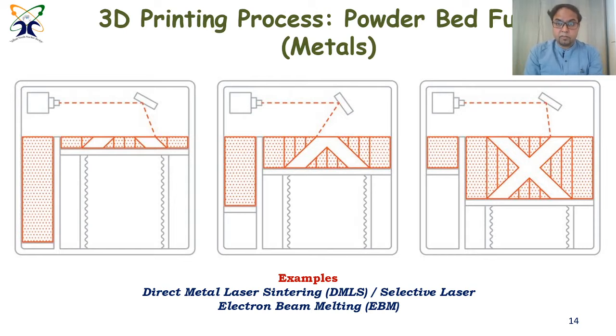This is another powder bed fusion dedicated to metals. Here we use a laser to melt the specific design or specific area, to melt the powder boundaries, to convert it into melt, and then fuse it to form a solid metal body. And this is very unique because the precision is high, you have high energy and a very penetrating, low diameter beam to make it more precise.